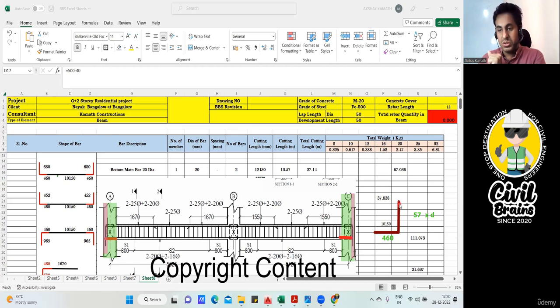Agree with me? This is the overall development length, which we saw is 57 times the diameter of the bar. In that, we know the horizontal is 460. So if I do the overall development length minus 460, will I not get this vertical height? Obviously, I'm going to get it. We'll do the same thing. I brought my cursor here, and what I've done is 57 into D. So D is the diameter of the bar. Right now I'm looking for a 20 diameter bar.